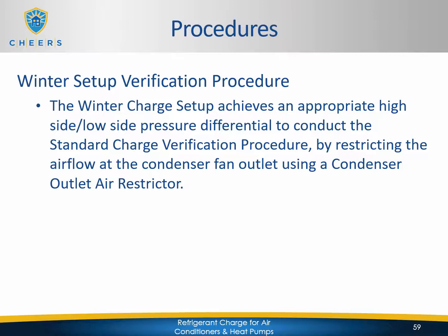The winter charge setup achieves an appropriate high side, low side pressure differential to conduct the standard charge verification procedure by restricting the airflow at the condenser fan outlet through the use of a condenser outlet air restrictor, which is that hood over the condenser that we showed you in pictures earlier.